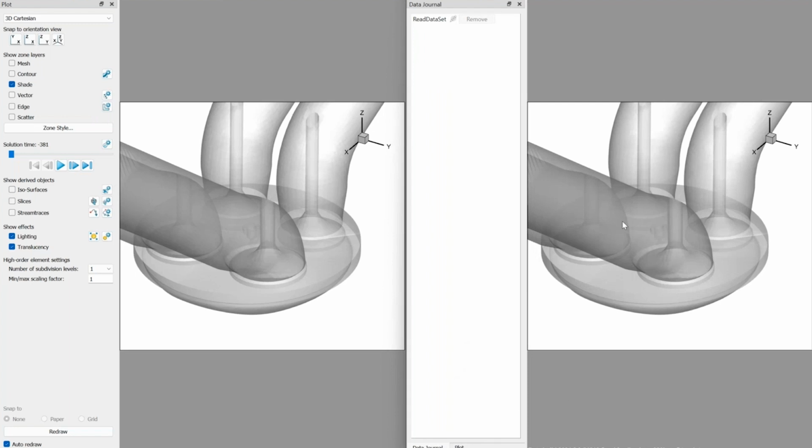Now, what I want to do in this case, going back to the keyframe image for this webinar, is compute mass flow rate through my exhaust ports. And so the exhaust ports are these 2 objects here towards the back of the geometry. And so in 2024 R1, what I have to do to compute mass flow rate is extract a slice, and I have to extract a slice such that it's isolated to these 2 regions. So let's go ahead and do that.